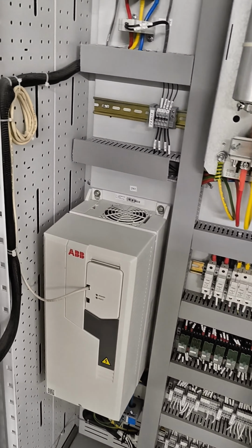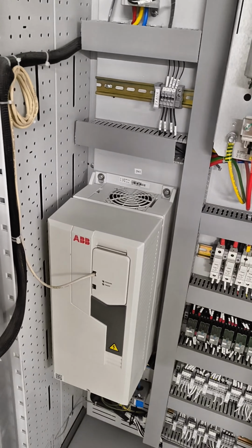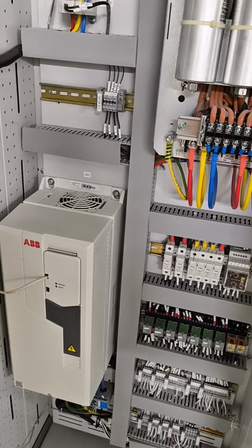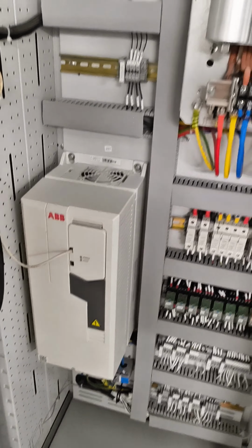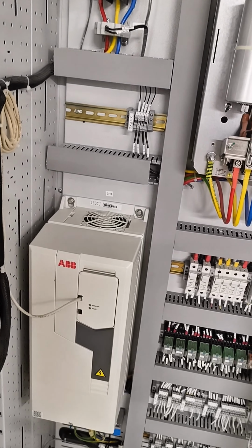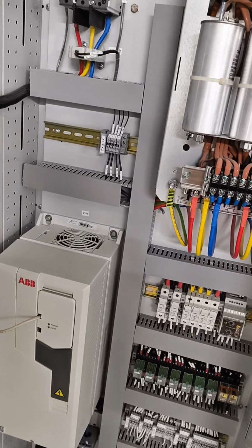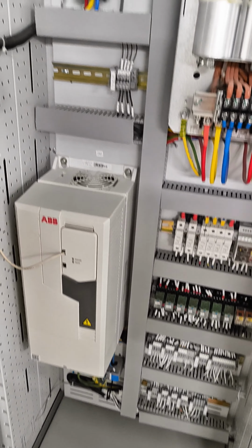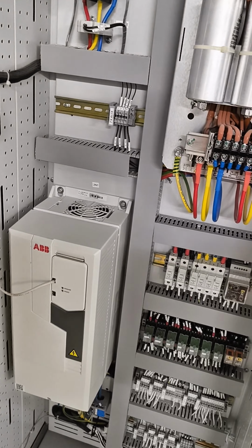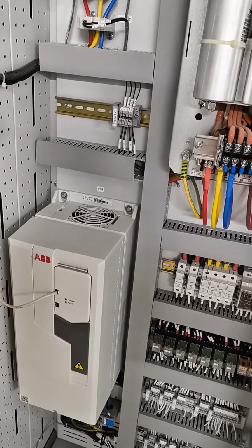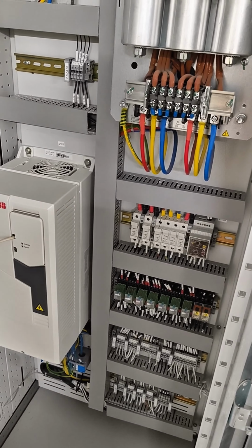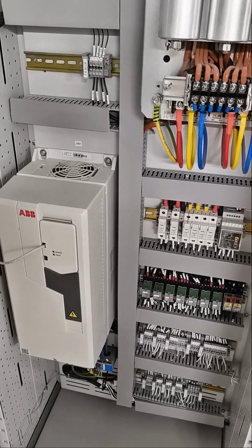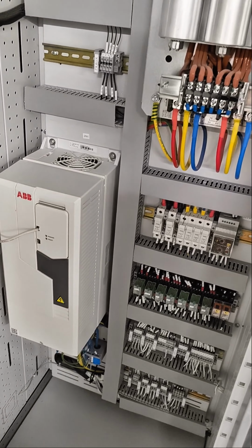And if the running hours exceed 2000 hours and we still did not apply lubrication on the bearing, what will happen? The bearing might be damaged because of insufficient greasing or deficiency of lubrication. Yes or no? If we constantly monitor the data, meaning running hours, and apply lubrication before the timeline, the lifespan of our bearing will increase. So if we have the appropriate data, we can maintain our equipment accordingly. Right or wrong?